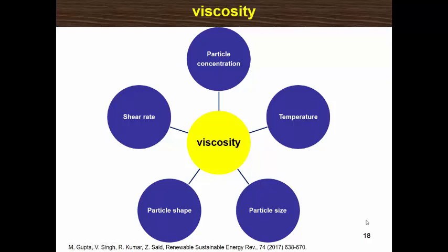Also, an increase in thermal conductivity and changes in other physical properties such as density, heat capacity, and viscosity are important indications to infer an improved heat transfer behavior. The heat transfer coefficient is truly the main feature of nanofluids that plays a key role in heat transfer performance. Results of almost all previous investigations show that the heat transfer coefficient of nanofluids is higher than that of the base fluid and increases with nanofluid concentration.